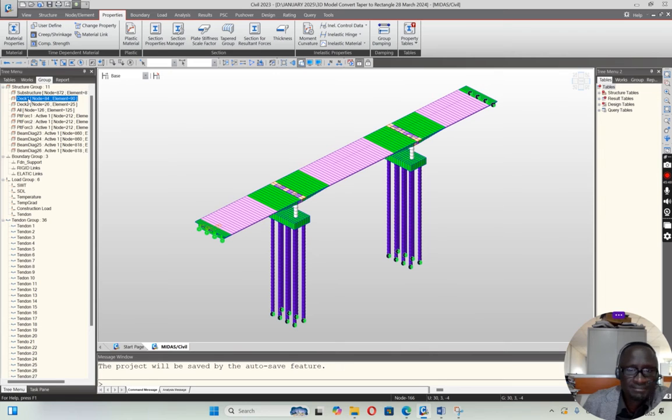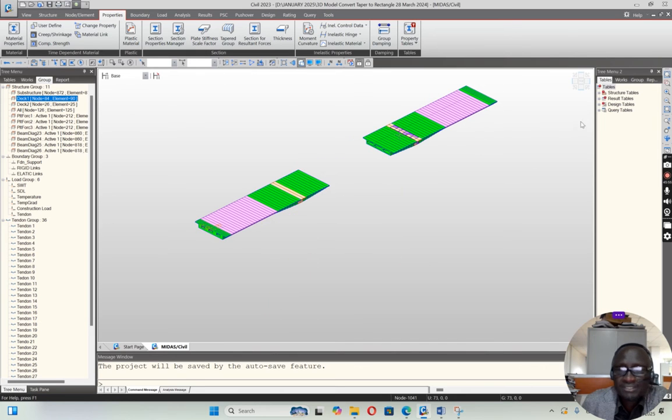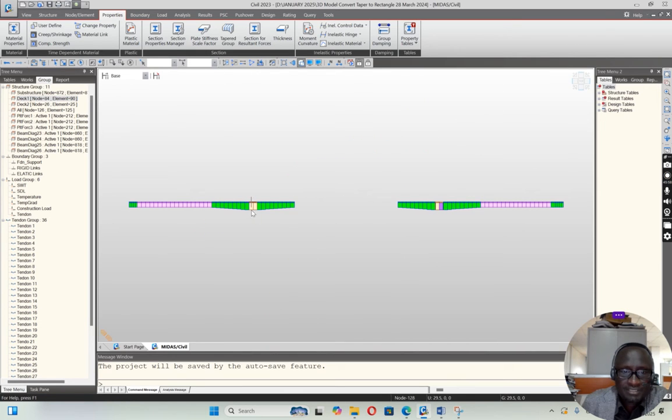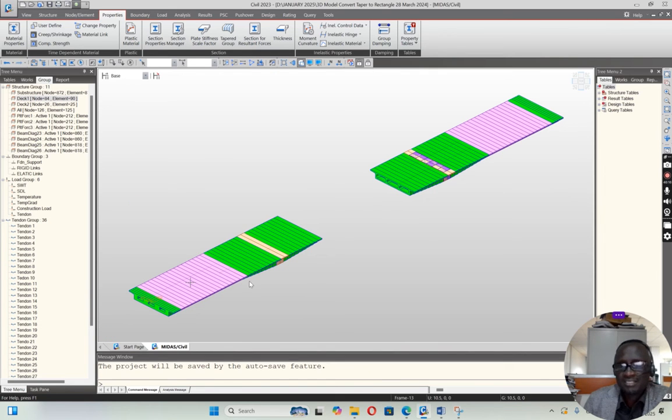Then if I want deck system, so I told you that this deck system is over this. So you are going to do the outer span. You leave the middle portion. This is 40 meters. Even though this is 66 or 99, you still have a lot of span here. Traffic will continue moving. So that is now that deck. So you can do it both sides, or you could do one and then you just continue. But I decided that since it is in a dry area, you can actually prop it. The contractor has capacity to do all that.